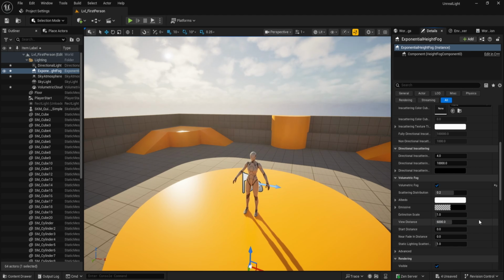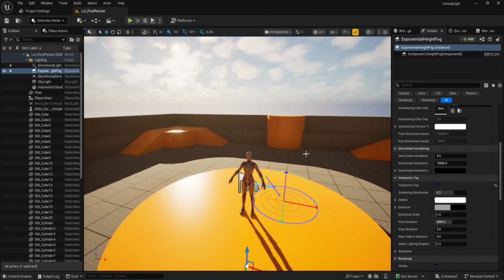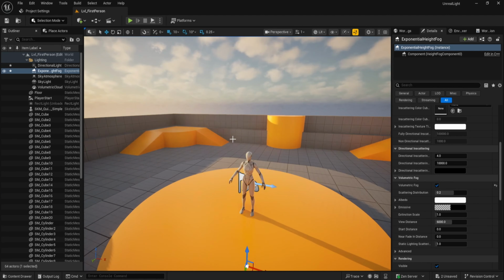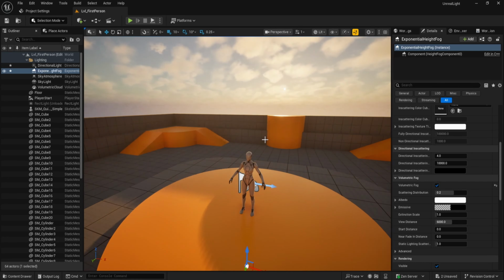And that's the complete environment lighting setup. We've got the sun, the sky, the atmosphere, the clouds, and the fog, all working together. With Ctrl+L, you can rotate your sunlight, adjust intensity and fog density, and instantly switch from clear day to dramatic sunset. This combination gives you a fully dynamic cinematic lighting system inside Unreal Engine.